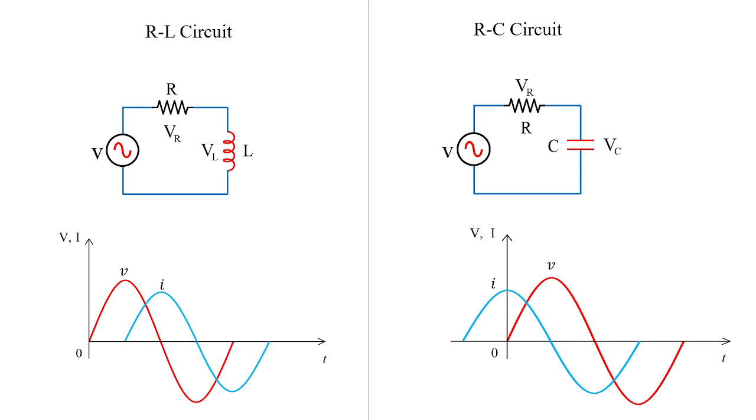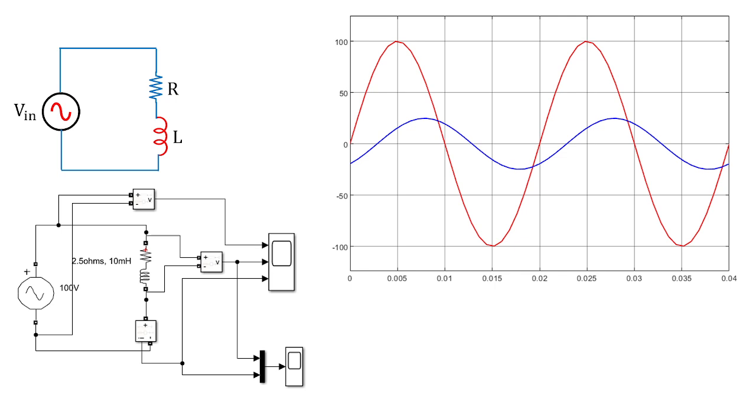So voltage and current relations, that is in lagging and leading, this can be purely observed with the help of MATLAB model. So here I'm showing you directly the MATLAB model where you have input source voltage, you have resistor, you have inductor, and this is a MATLAB circuit connected over here where you can see the input voltage is 100 volts. Okay, and RL circuit is connected and voltage is measured across RL circuit. So that voltmeter is going to give you the waveform of voltage across RL.